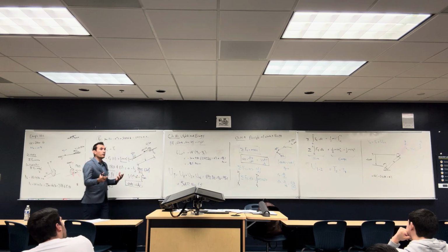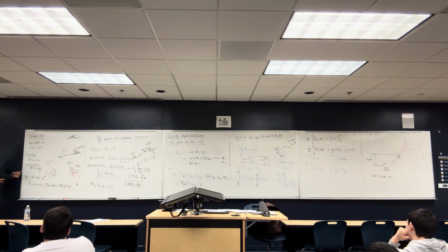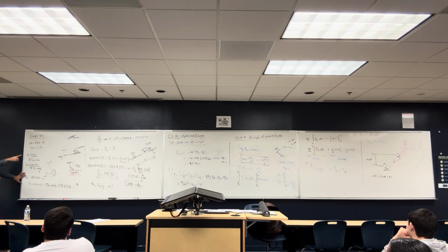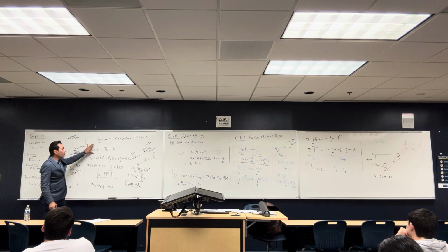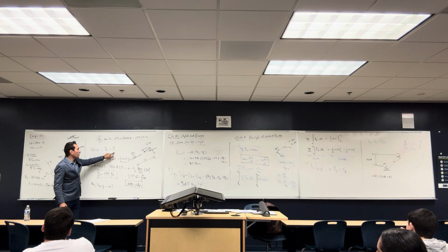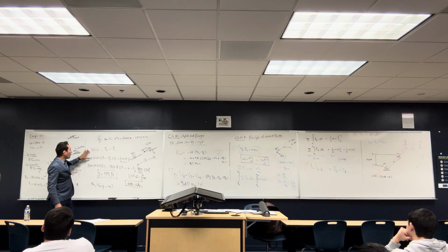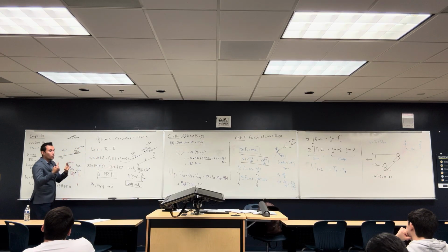So basically, you can solve this problem using Newtonian kinetics by itself, but you are going to take 2 steps. The first step is that you have to solve this equation. That's step number 1. Step number 2, once you solve this equation and get a, you have to go to chapter 12 to get s. So you use 2 chapters to do this. But with work and energy, I only solved one equation: U equal to T2 minus T1. T1 is equal to half m v0 squared, and T2 is equal to 0, and I only want to find these forces, so it's only one step.